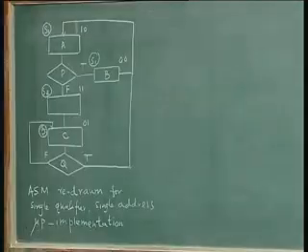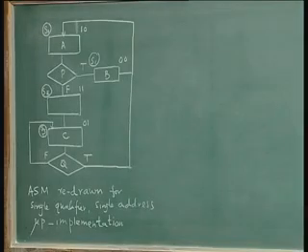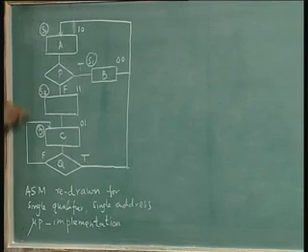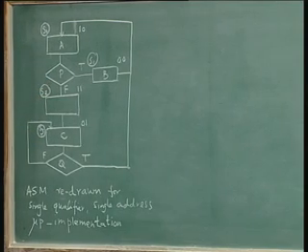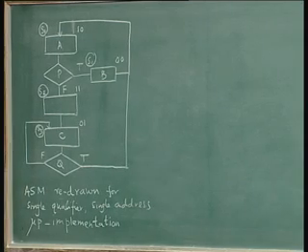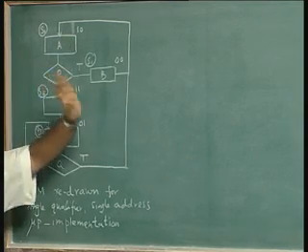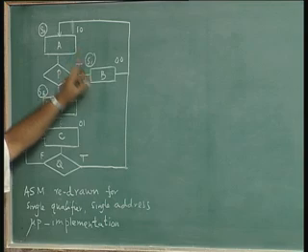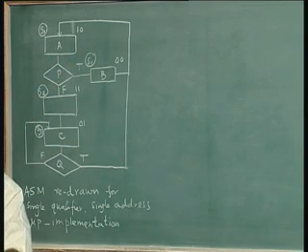So, we will take the same example of the ASM that we took in the last lecture, where there are only 4 states S0, S1, S2, S3, 2 qualifiers P and Q, and 3 outputs A, B, C. The only change I have made, in fact we did it in the last lecture itself, is the assignment of the states. Earlier I had taken arbitrary assignment, I had called it 0, 1, 2, 3 corresponding to S0, S1, S2, S3, now I have made a slight change in this.